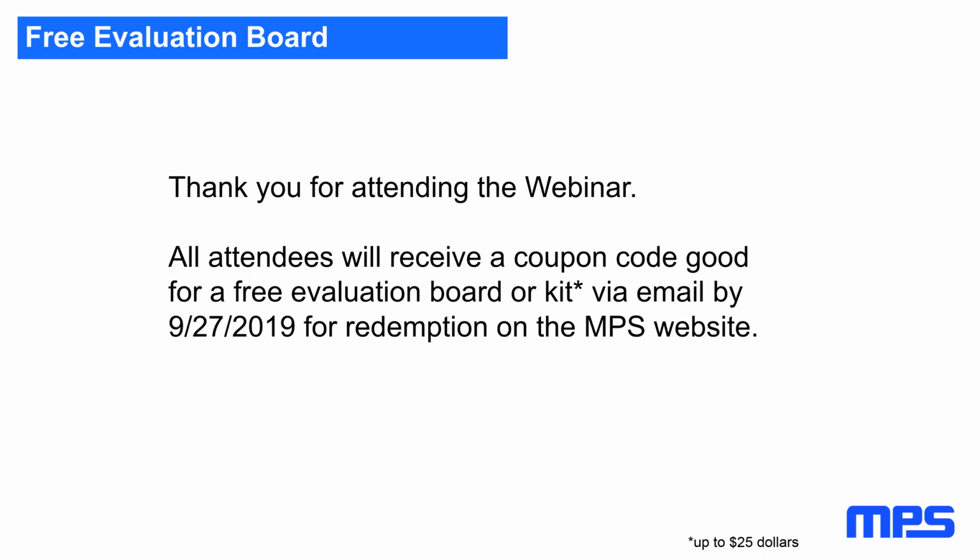Next question: why is a cutout area provided in the PCB layout for an isolation circuit? What is this effect exactly? The noisy eddy currents you create in a local plane, you do not want to have them distributed to the outside, because current in any conductive material which is not superconductive will create voltages, and you do not want to have these voltages outside, so that you have a voltage source in your harness between different positions of your PCB.